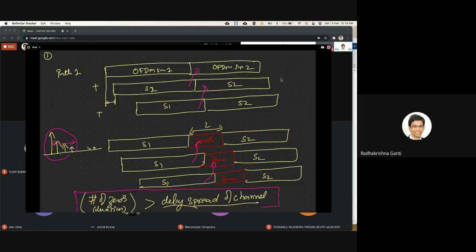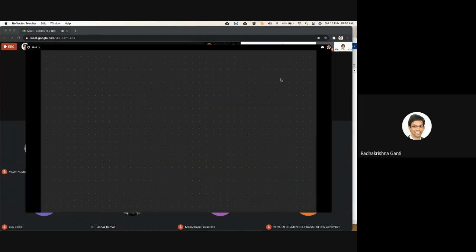One thing is important: you could have put zeros, but this is a waste of resources. You are not transmitting any additional information there. They're a waste. So the number of zeros should be greater than the delay spread of the channel. Good. That's one point to remember.